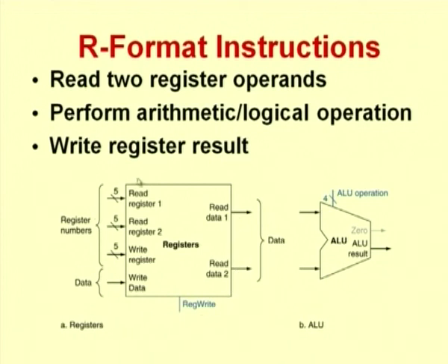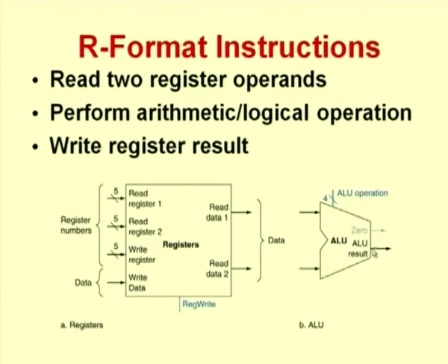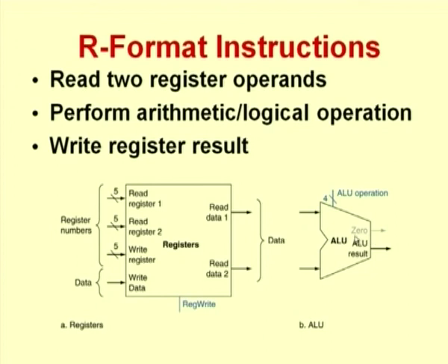So, you can see that the register file will consist of all these elements and the control required to generate all these elements correctly. Similarly, if you look at the ALU, it will require 2 inputs which are coming in, and then the result of the ALU will have to be stored somewhere, and what operation actually needs to be done also has to be specified. In addition to this, when an ALU operation takes place, certain conditions may be generated. For instance, you may want to check whether the output of the ALU is 0 or whether a carry has been generated when an addition is happening. You may want to do some of these things. In those cases, we will have these different control signals that are generated. So, that will be specified over here. So, this is for a simple R format instruction.